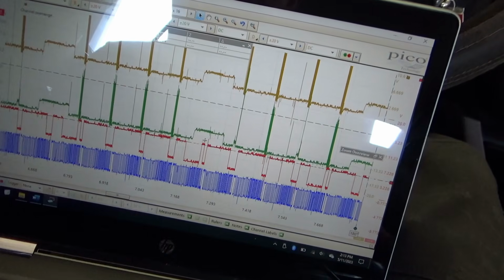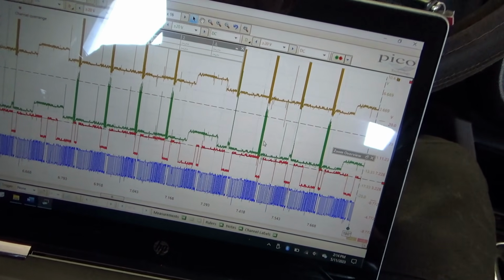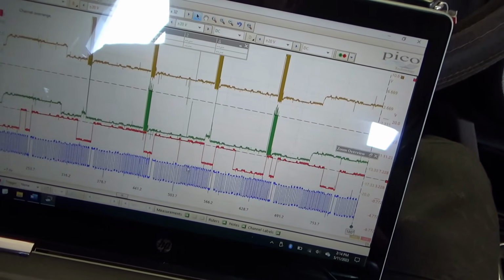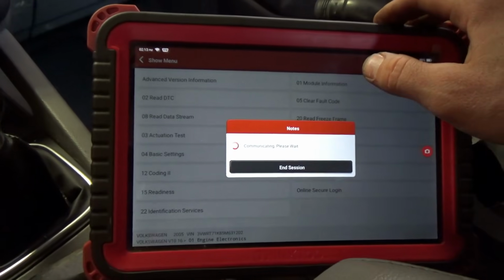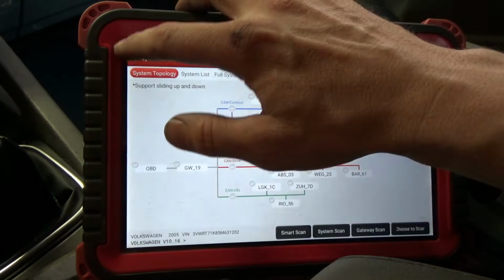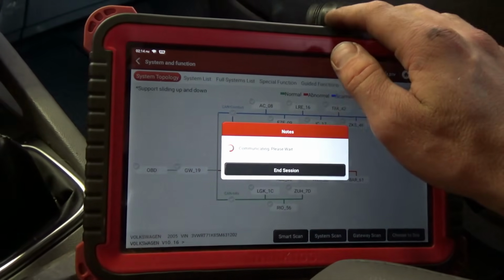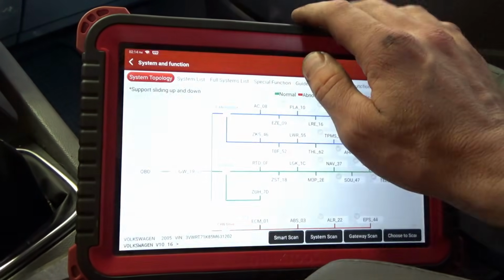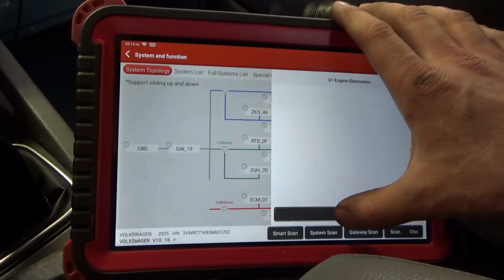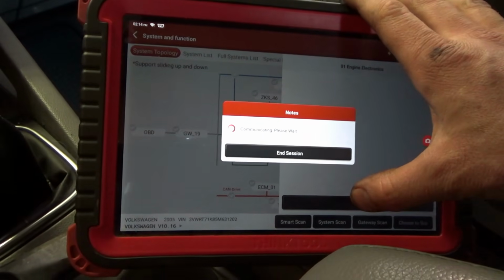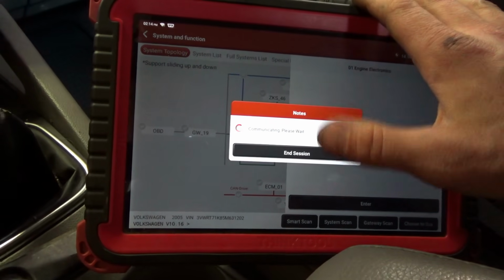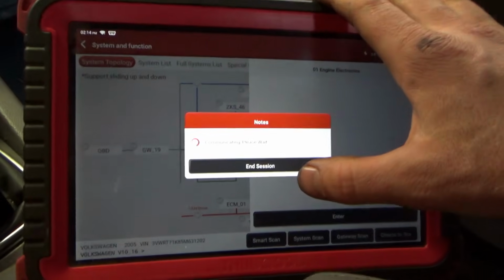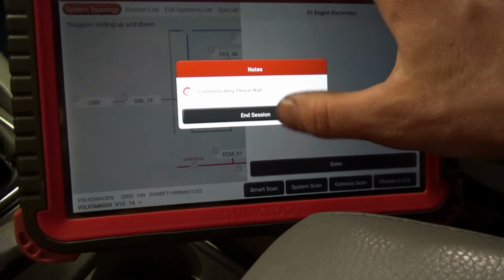Waveform. But you can see nothing changed with the injectors at all. It fires there. And I'm sure now we set a 341 instead of a 3007. Let's see here, ECM. Like I said, I've never seen a crank with 2 sync notches before. But then again, the other VW did have 2 sync notches per crank revolution.